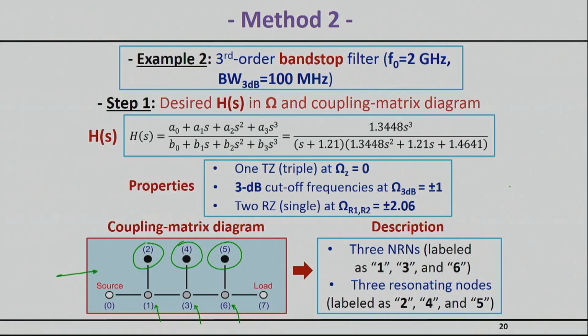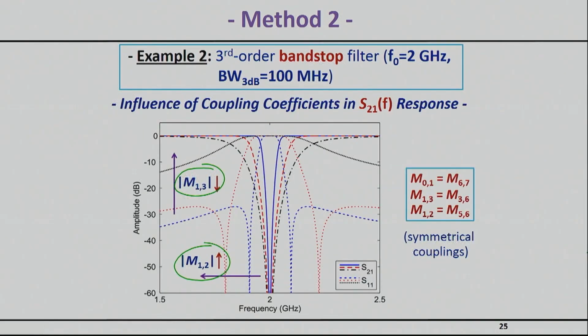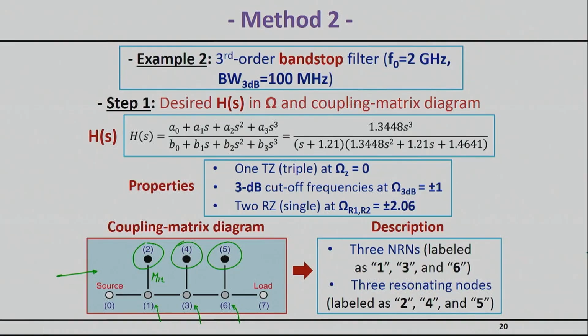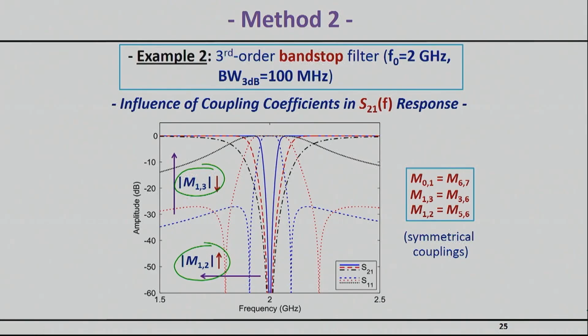here's the M12. So M12 is a coupling between basically the filter structure and the first resonator, and similarly, the M13 is this coupling here between the first 2 non-resonating nodes. So if you're interested in, or worried, what will my filter do if I make a mistake, a fabrication error, for example, you can very quickly isolate just these 2 effects and then replot the frequency response that you see here. So for example, you will see that with the M12 here becoming higher, you're basically broadening your bandwidth.